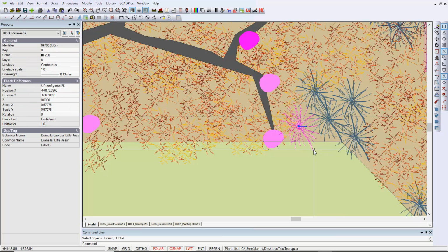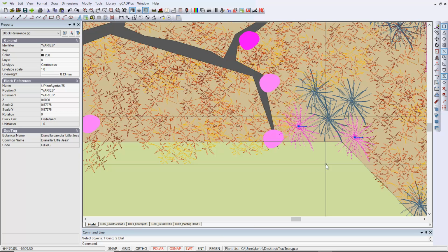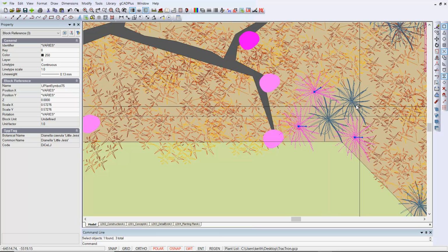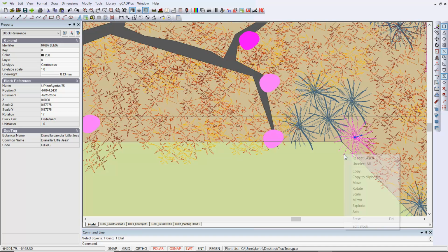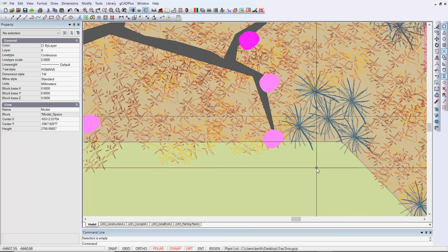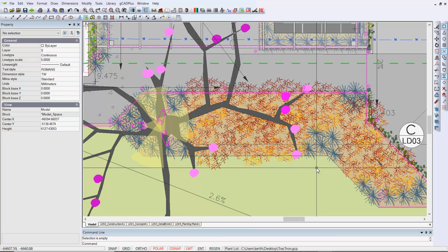See how if I pick each one of these symbols here, the rotation angle is the same in all of them. That adds to some repetition. So just move those around, give them a different angle. You might even just pick the symbol and right click and scale, and just scale things up and down a little, just to put some variation in. So I hope that helps.